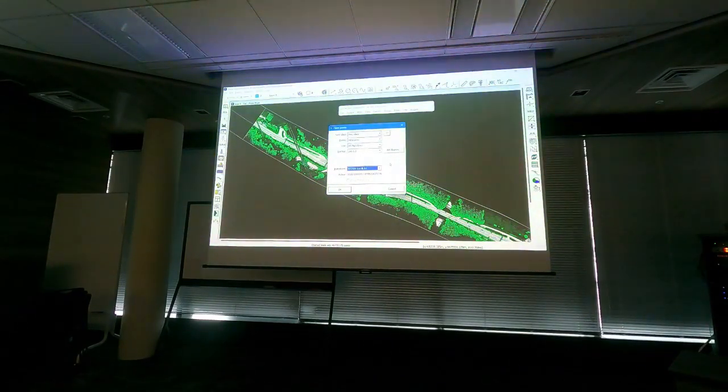So I opened a block from a project where the project has the information on the projection system. So the software knows what is the active projection system. And then if I do save points as, and I select an LAS format or a text file format, I can select WGS84 long lat in the transform field without having a transformation defined for it.